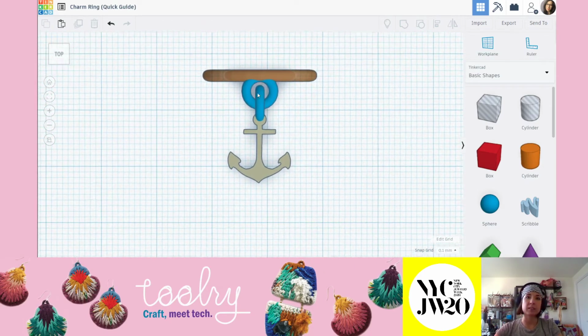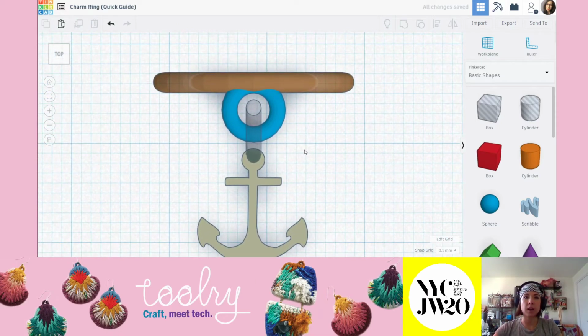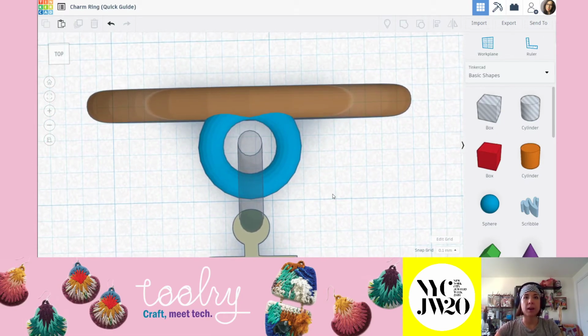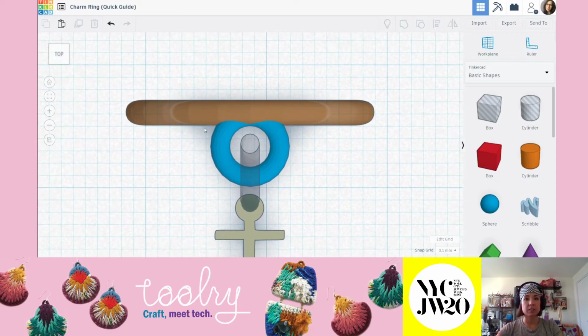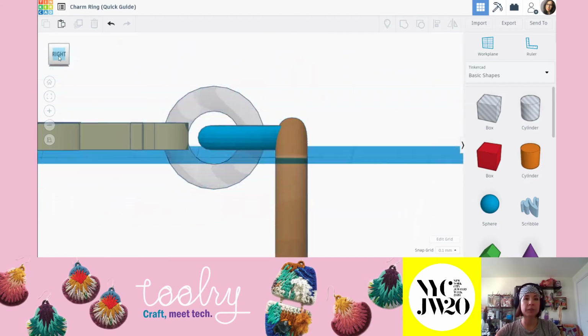At this point, what you can do is turn this to be a hole temporarily. The reason is that when this is a hole, you can see through it and see what's happening all around this. Remember how a little bit ago I said that you can fabricate this entire piece as one assembled part, meaning it's 3D printed in one assembled part and it's casted as one assembly. You can do that as long as you have enough room around all of these objects which interlock. That means spacing around here and spacing here. So any object that is interlocking has to have 1 millimeter of clearance.